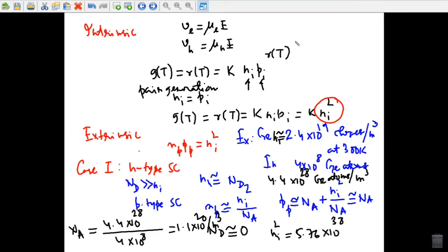Even at moderate temperatures, they get excited into the conduction band, leaving behind an equal number of holes or vacancies in the valence band. In a pure semiconductor under thermal equilibrium, the number of electrons and holes are equal since they are produced as electron hole pairs. So these holes attract electrons in the process. One of the neighboring electrons will jump to fill the vacancy. This process will continue and is identical to vacancy diffusion.